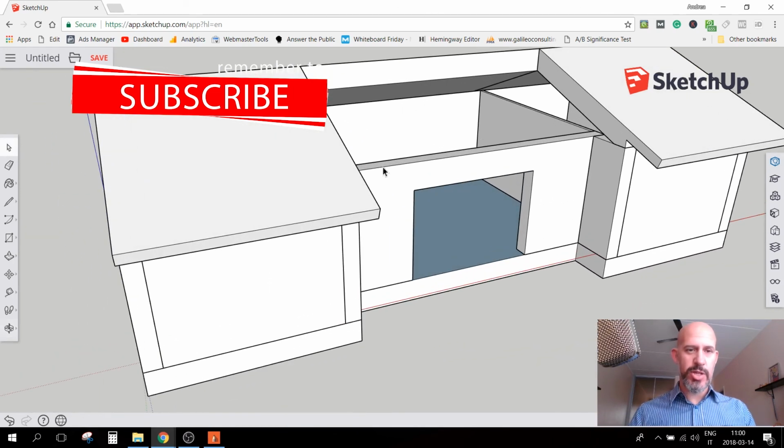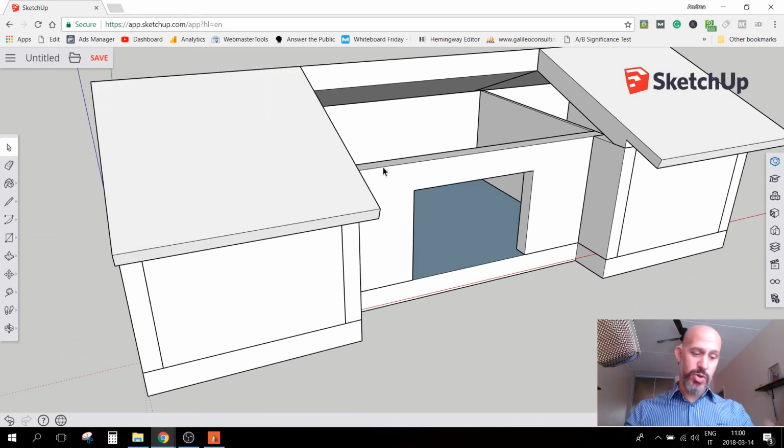this demonstration, which was to show you how easy it is to draw with SketchUp and how you should think in terms of thickness of walls, that you should always consider the components that are manufactured in the factory, they have given thicknesses, and you should investigate to find out which are the proper sizes for each type of wall.